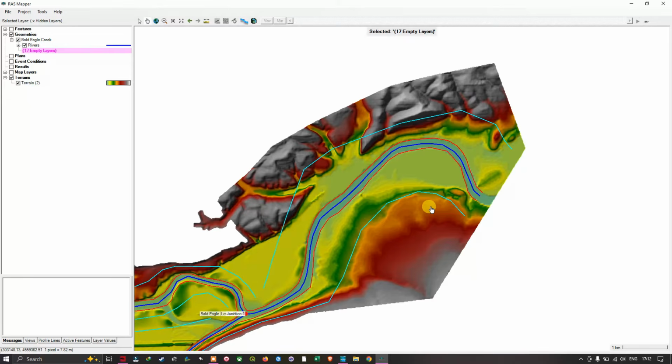For example, we're gonna use this particular tool called measure distance here. So I'm gonna click this tool. Let me check this particular length as the cross section difference from one cross section to another. You can see it is around 611.2 meters. This is the distance between the two cross sections. So every half a kilometer, we're gonna create another cross section.